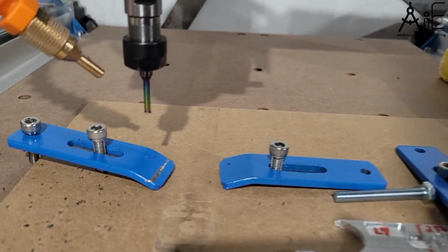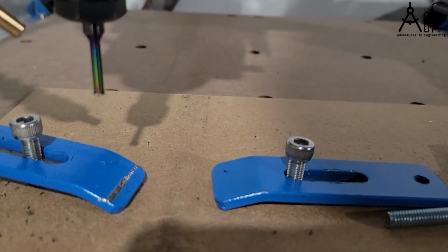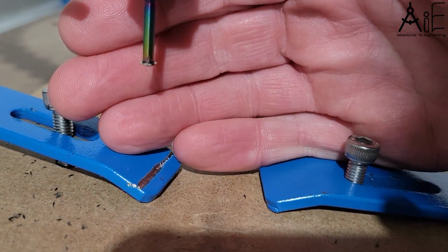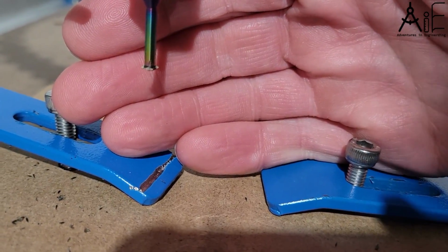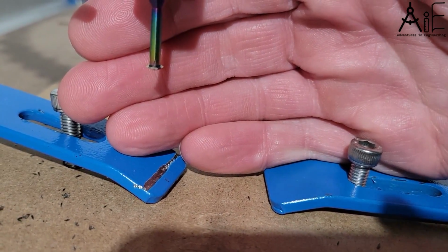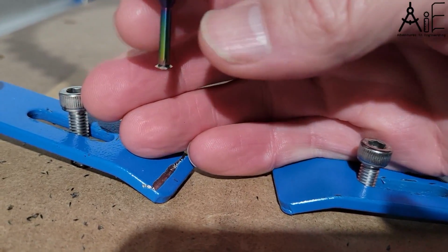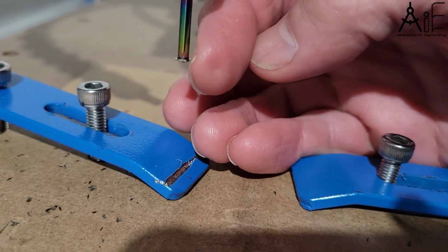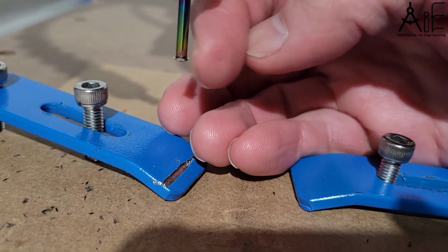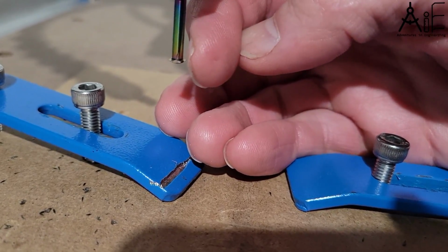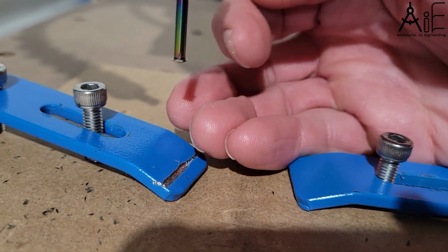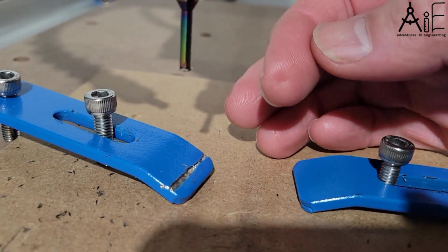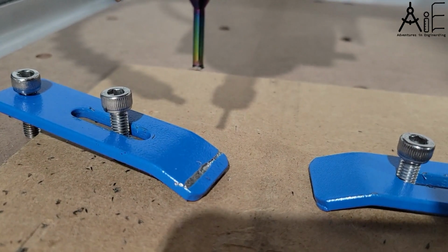A thread milling bit looks like this. This is a single flute, or a single tooth, thread milling bit. And this is a really nice bit because it allows you to do many different thread pitches. This one happens to be, I think, about 3 millimeters thick here and 4.9 millimeters thick at the edge of the teeth. So since I'm doing millimeters, the smallest I can do is a 6 millimeter thread. However, I can go, I think, all the way up to 10 or something like that with this same bit, and of varying thread pitches.